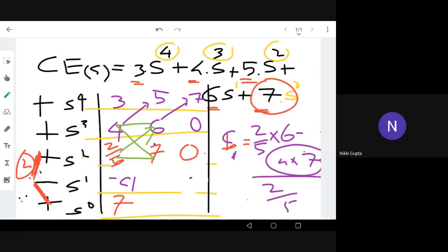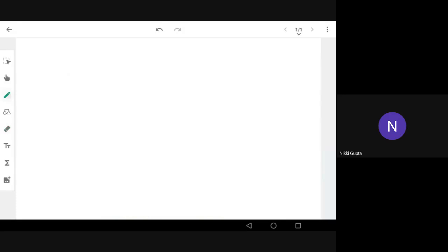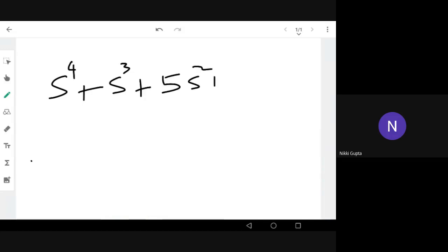There are two special cases I will tell you so that whatever question comes in the exam, we can try this Routh-Hurwitz criteria. And this is asked in a lot of competitive exams where they will give an equation and you need to find. So after some practice, you can immediately see that some systems are unstable. For example, if I write a system like this, s raised to 4 plus s raised to 3 plus 5 s squared plus s minus 2, it is stable or unstable, we can immediately see that this is going to be unstable because there is a minus here. Right. So likewise, we can see a lot of things as you practice a lot.